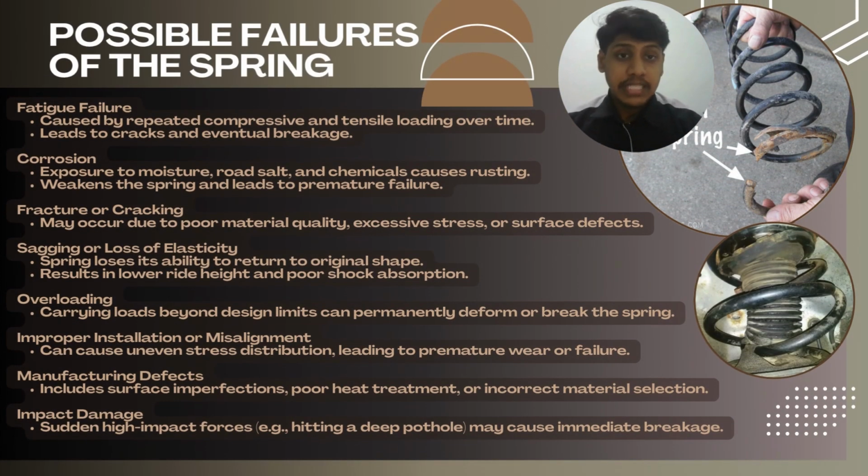So now I will be explaining the possible failures of the spring. There are several failures that can be found in a spring. First is fatigue failure, caused by repeated compressive and tensile loading over time, and it leads to cracks and eventual breakage. Secondly, corrosion, due to exposure to moisture, road salt, and chemicals, causes rusting. It weakens the spring and leads to premature failure.